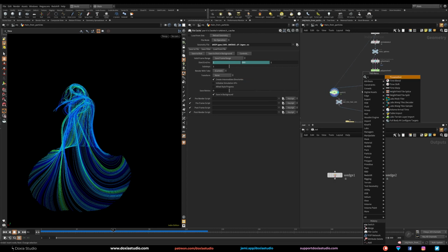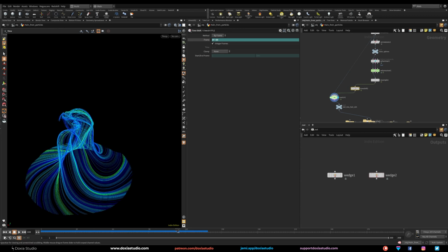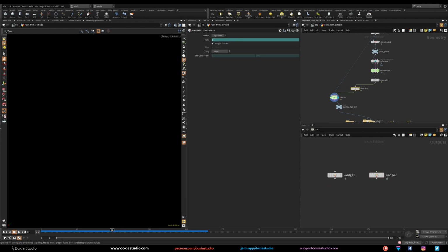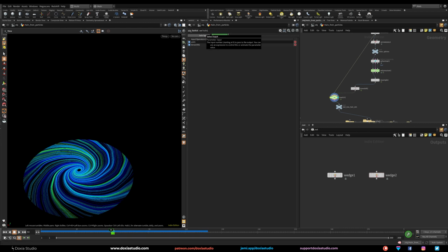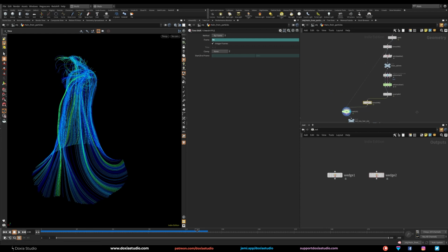So what we need to do is just add a time shift here, and we are going to do a little animation, a little expression that is going to -60. Okay, so now it will behave like we want. Because as you can see with that little time shift, on frame 61 we are using frame 1 from our Vellum Hair. And I can see that I did something wrong here. So the keyframes we need to change here. Go to 1, and on 60, stay on 0. Okay, and we can clean this one. Sorry about that. So on frame 60, keyframe 0, and then on 61, change to 1, and then this time shift will now work. As you can see, we have our particles forming our hairs, and then boom, they will be advected. Cool, very simple.